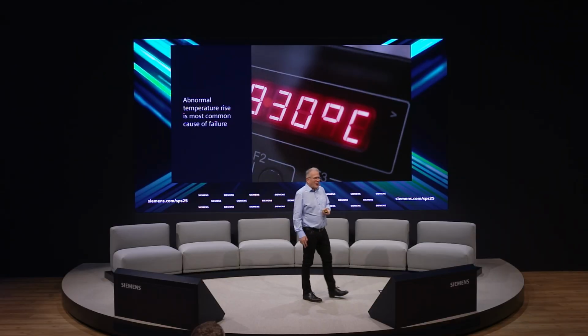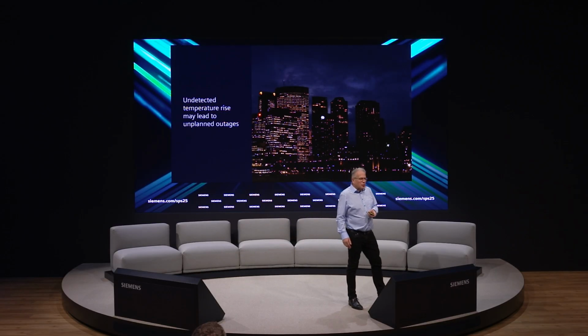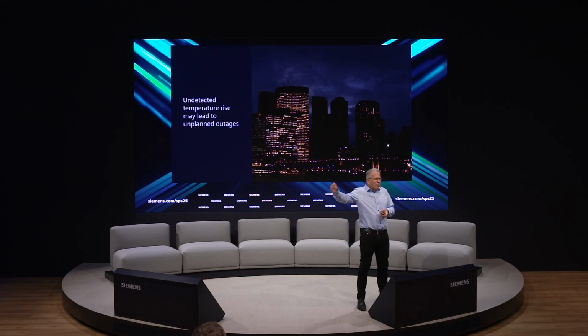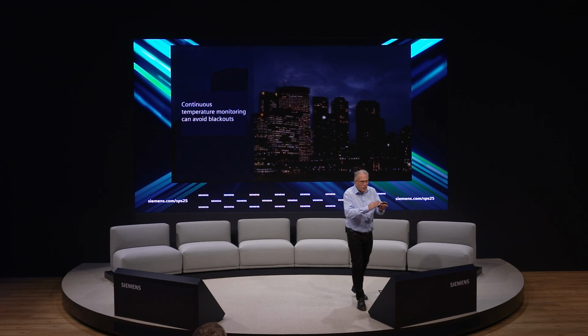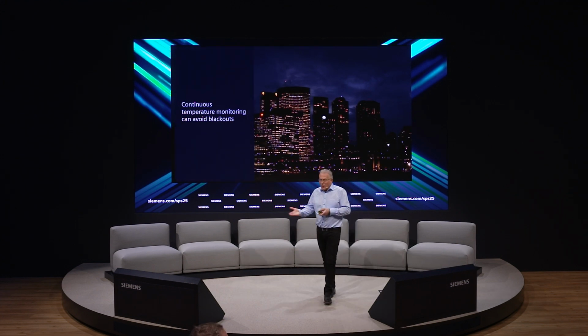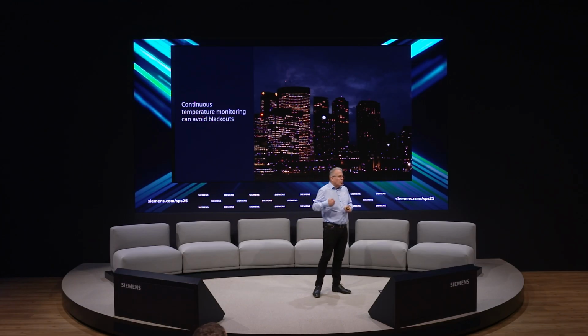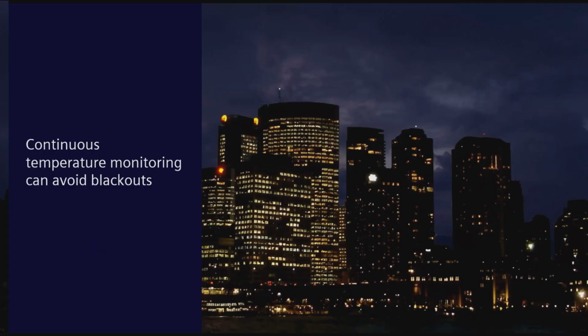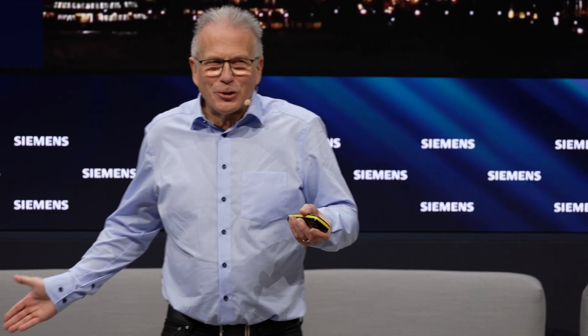So, and for this, we are introducing a new system that we put along the busbar run, temperature sensors in it. So we allow to have a continuous temperature monitoring, and that can avoid blackouts. And you are able to react before something happens because you see the increase of the temperature. So stay tuned. It will come in the near future. Then we will introduce it officially, but this is only a forecast for this.